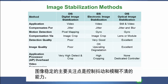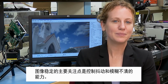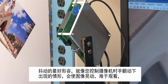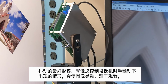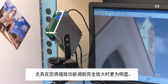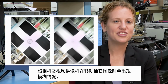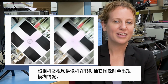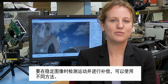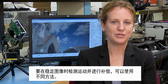The primary concerns in stabilization are the ability to control jitter and blur. Jitter is best described as what happens when your hand shakes when controlling a video camera. It makes the picture shaky and difficult to watch. This is especially apparent when the zoom is fully extended. Blur happens on both still and video cameras when the camera is moved while the camera is capturing an image. To detect the movement and compensate for it while stabilizing the image, various methods are used.